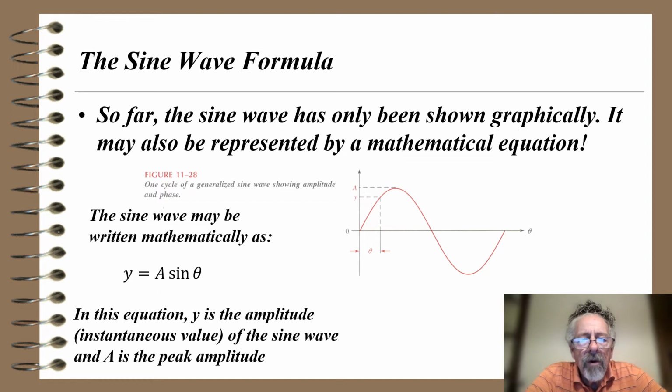Sure there is. So far, the sine wave has only been shown graphically. It may also be represented by a mathematical equation. So here you see a sine wave that has a peak value of A. We see an angle of theta, which gives an output of y at that angle of theta. The sine wave may be written mathematically as y equals A sine of theta, where you can get the instantaneous value of the sine wave at any value of theta. In this equation, y is the instantaneous value of the sine wave, and A is the peak amplitude.